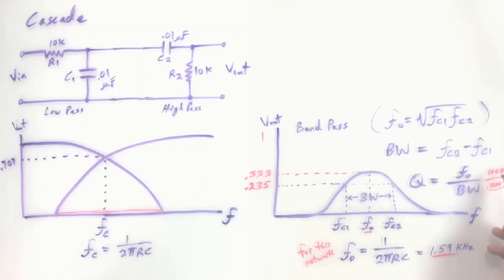I think you can see that seems like a very wide filter, doesn't it? It'll let everything from 100 hertz down to zero and 100 hertz up to 200 hertz. Again, I didn't mean to center it algebraically like on a number line. It's a logarithmic center, but I'm going too fast.